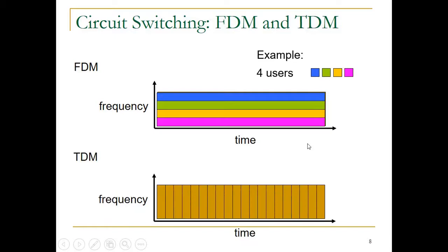Okay. Now, on the other hand, when it comes to time division, it's the same frequency that's been allocated, but instead of being divided at the base of the frequency, we use time instead. So for that same frequency allocation, per given time slot, we can slice it up into time slots and reallocate them for those 4 users. If you look at this carefully, from time one to time 4, the 4 users have a slice of the entire frequency to operate within at specific time slots.